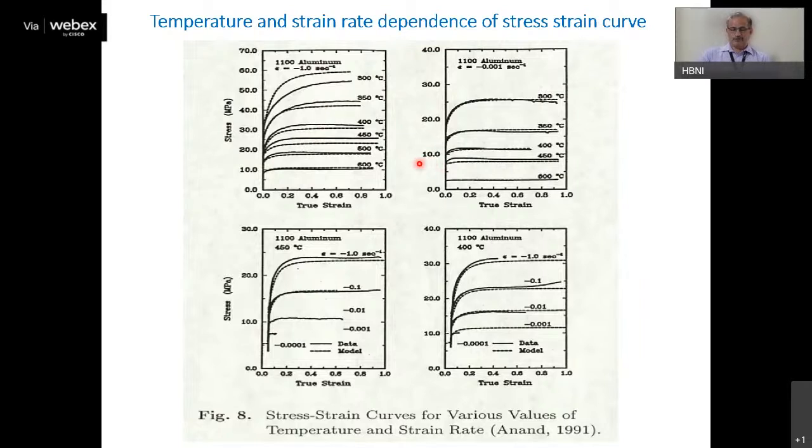And if you apply a large strain rate, with strain rate, actually, the yield strength increases. So you reach the plastic region at higher stress values. So under shock compressions or under dynamic loading, you can reach higher yield strength states as compared to the static. So this is definitely strain rate as well as temperature dependent.